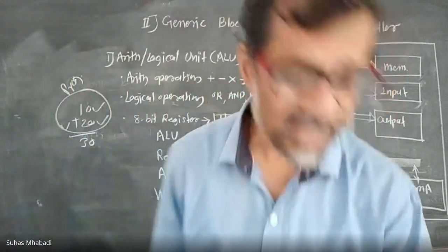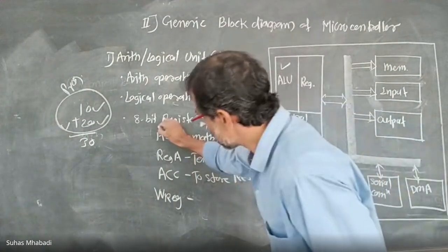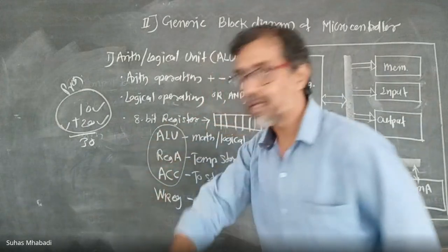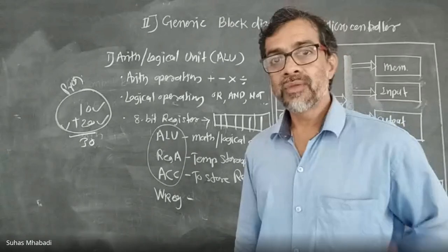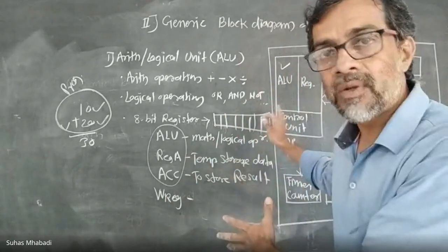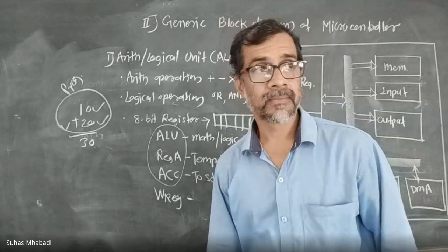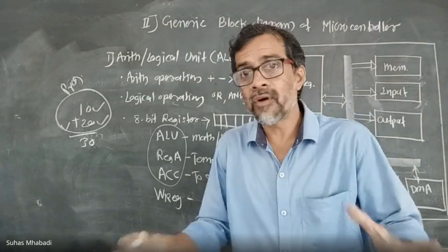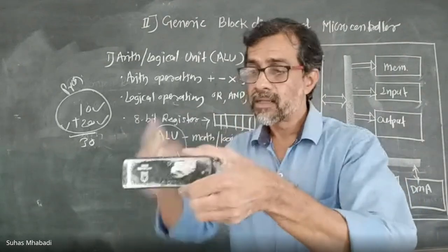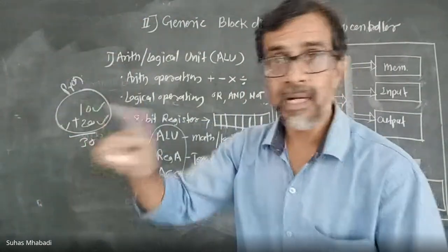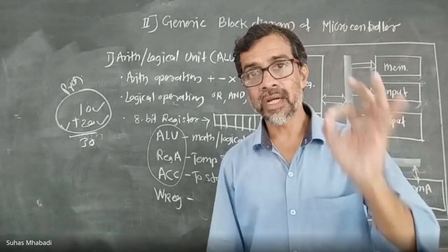Normally, the devices which are developed by Intel, they used to call it only ALU, register A, or accumulator. But now this controller is developed by Microchip Corporation. They said that I will offer a different name. So the same register, used by Microchip and not by Intel, that time is called the working register.